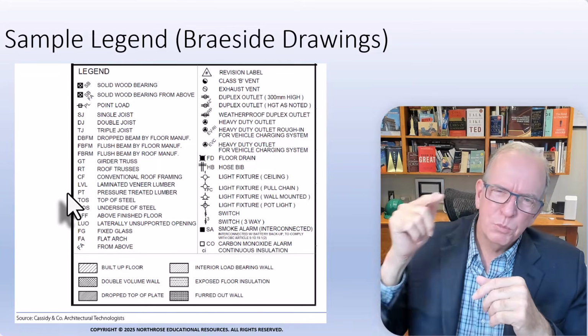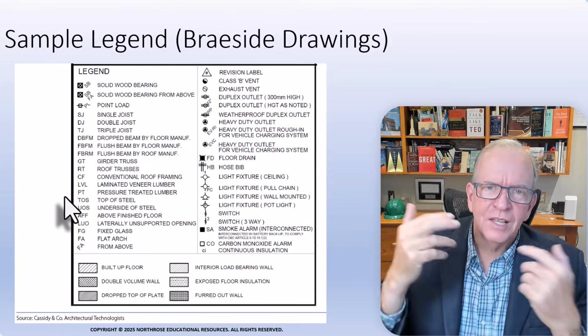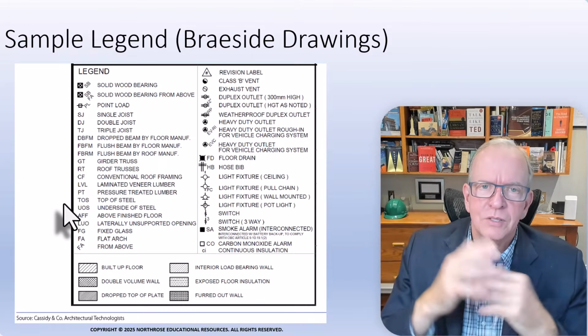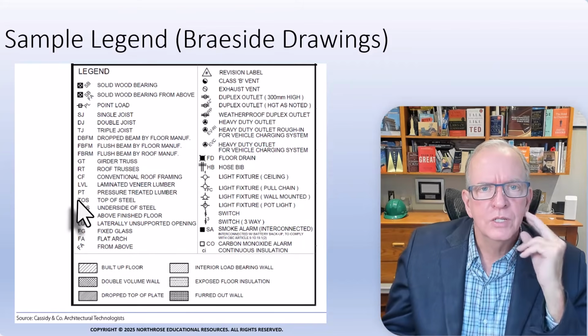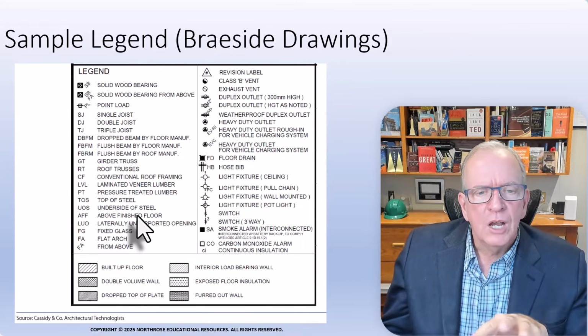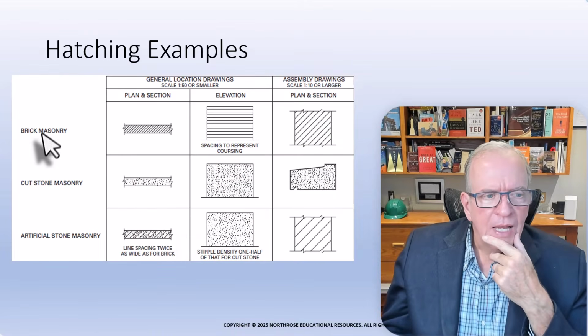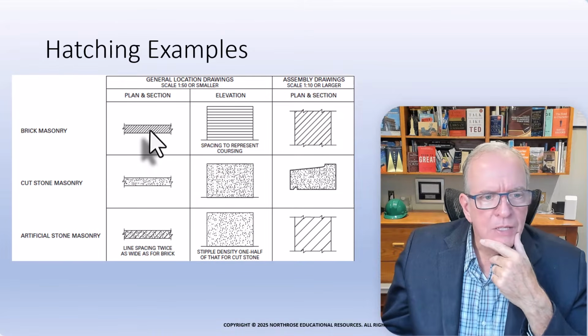So I've seen one letter or abbreviation used in 4 or 5 different contexts, but if it's pointing to a hatching that is a standard insulation hatching, that gives me a clue that, oh, it's talking about the R value of the insulation. So it's all in relation and context of what you're looking at, and you have to build up a little bit of experience.